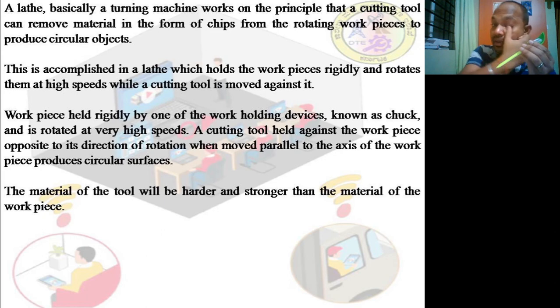If it is discontinuous chips, it will be small particles. It just comes out. There will not be any continuous threading. It will be discontinuous. Are you getting my point? So that is what we call discontinuous chips. The continuous and discontinuous chips depend upon the speed, feed, depth of cut, all those things will come into the picture. Let us not worry about it.